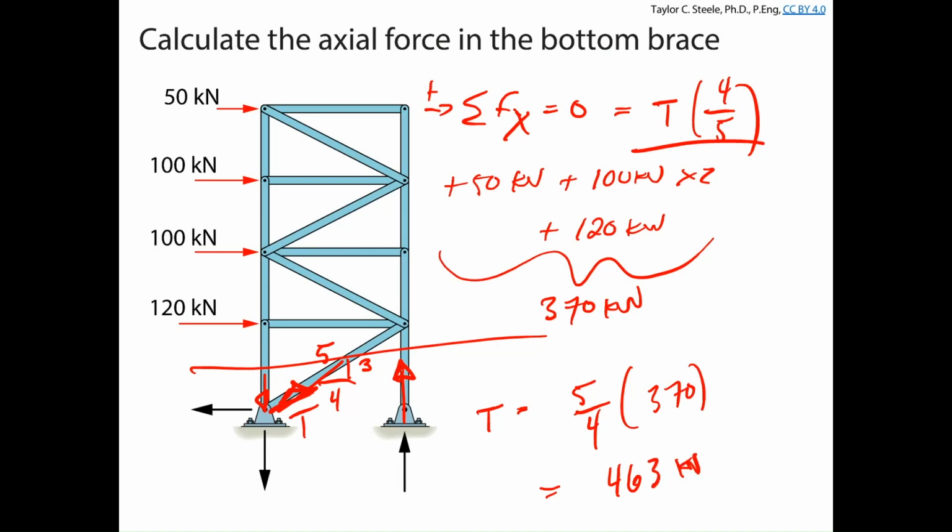Right, so just practicing again that method of sections. When we've got vertical members, it's very easy to apply equilibrium in the x direction to figure out how big that force is going to be. You're going to be doing that lots of times on your assignment, so it's important that you're able to do that. Does anyone have any questions or concerns about that problem before we continue on?